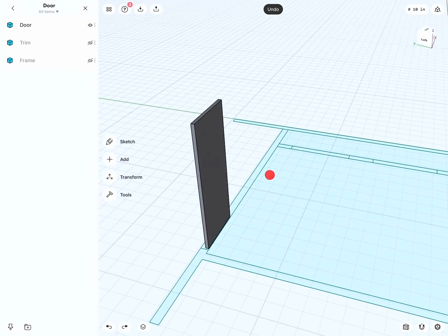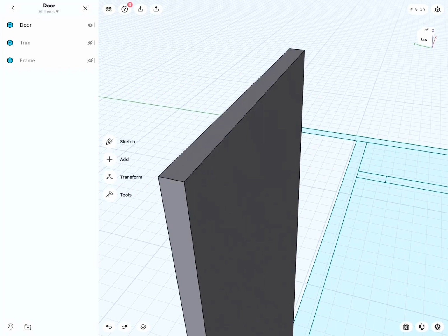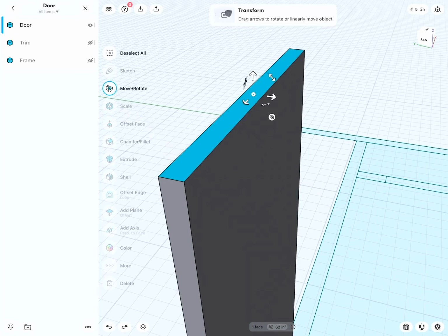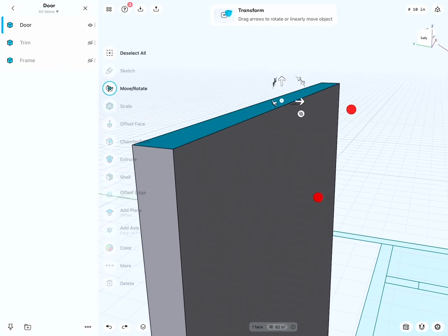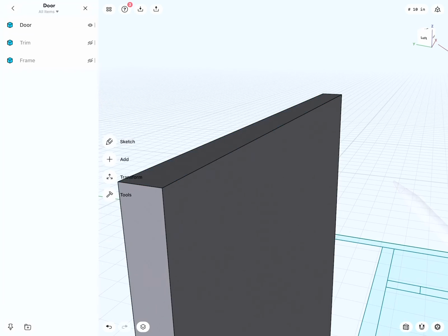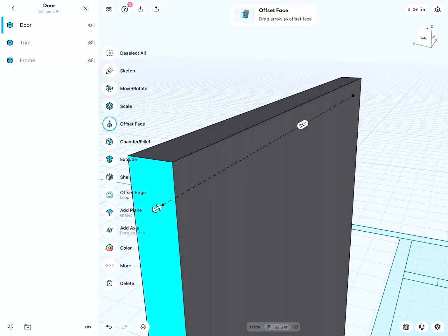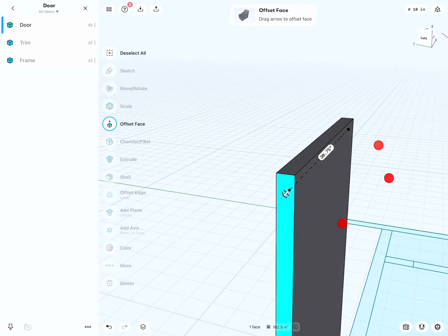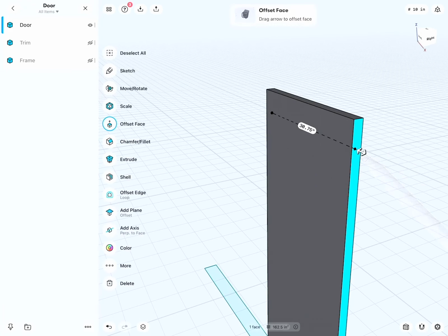If I would like to have a very particular way to move individual faces, I simply can select a face, go to move, and then I move this one down, maybe by a 1/4 inch. Go to here. So when this is, for example, moved by a 1/4 inch, then this would be 30.75. And then I go to the other side, and this is now 30.5.